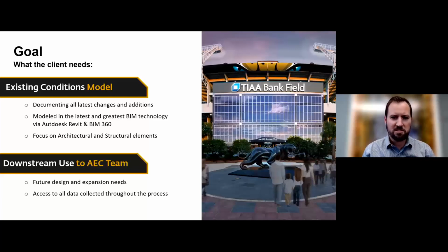The existing conditions model was number one. So we needed to document all those changes and additions over time. We wanted to ultimately convert all that into Revit models that are up to date, especially the architectural and structural elements. Then we wanted to downstream all of that data to the awarded AC team for any new renovation expansion projects to come, as well as all of our raw data collected, scan data, point clouds as well in that process.